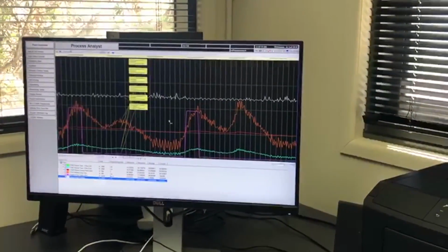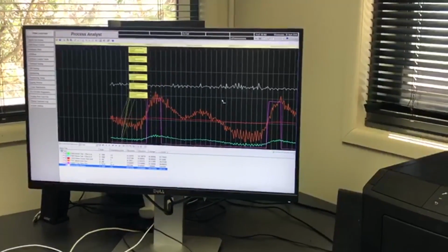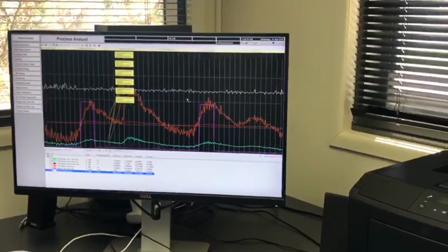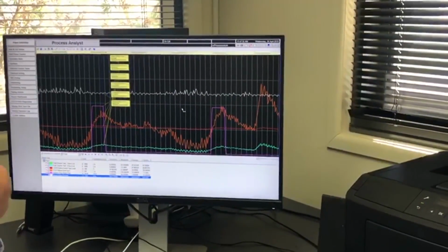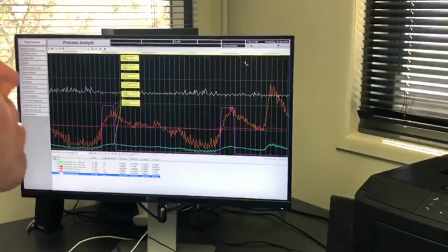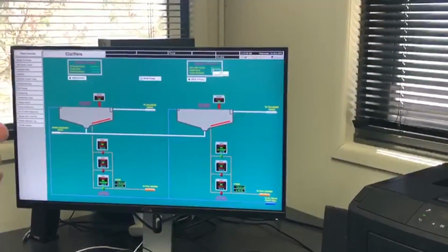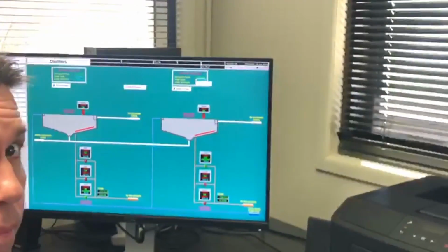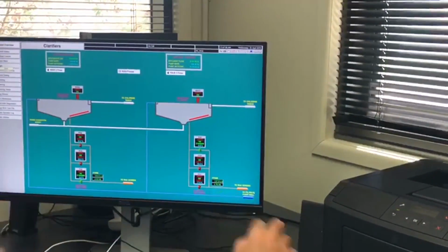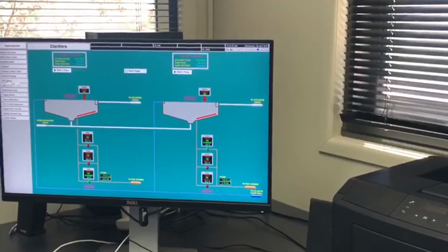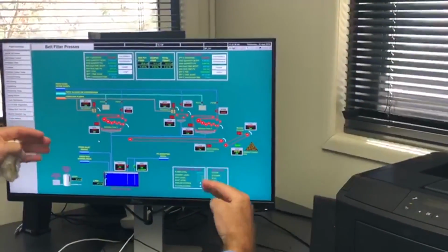The SCADA system also controls the plant's equipment. It doses the chemicals correctly in each step, runs the pumps, injects the chlorine in the disinfection process, and even adds oxygen by mixing the water in the bioreactor. It also provides a responsive and effective alarm system, coming up with any failure or fault process and even inconsistent readings.